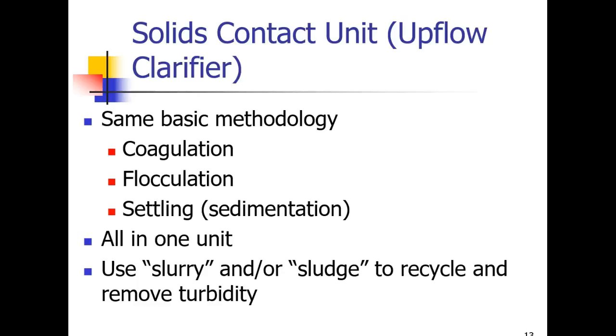So a solids contact unit is also called an upflow clarifier. We have coagulation, flocculation, and the settling, which is the sedimentation, and it's all in one unit. You use a slurry or a sludge to recycle and remove the turbidity.